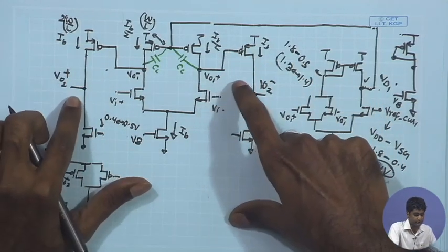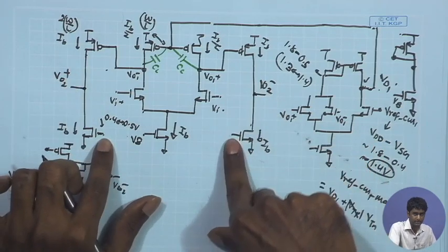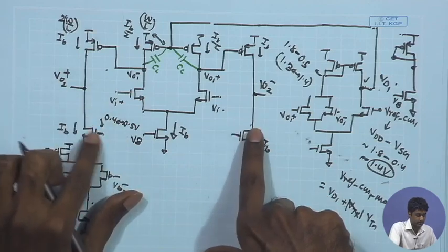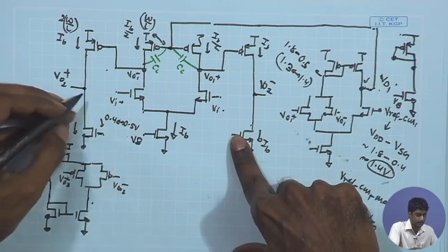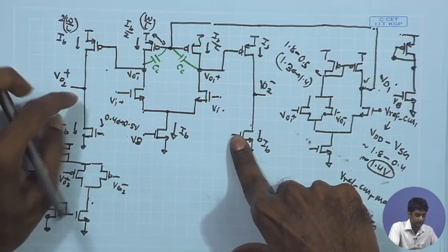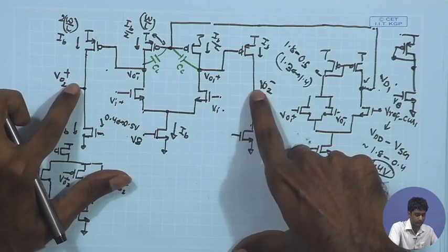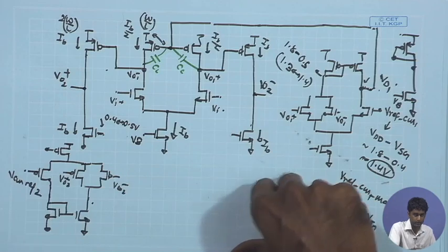The only option is to increase this gate voltage so that the VGS term in the equation becomes larger. As a result, it will be able to support the same current with a smaller drain to source drop, so it will bring the DC point over here lower.